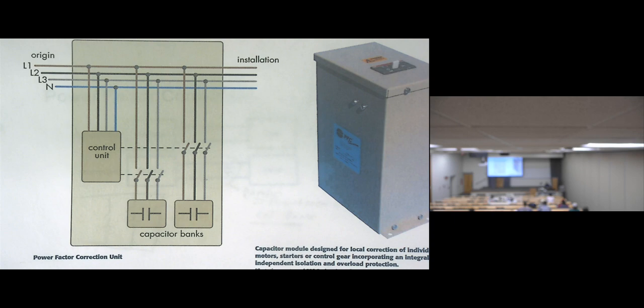Sometimes we have capacitors and we have something else called inductors, switching inductors. These inductors or capacitors will be added depending on the load. Most likely when there is no load, at night for example, in some high voltage areas, the load is very low. Sometimes the voltage will be very high, so we need to reduce it, to slow it down. Then we turn on the inductors.